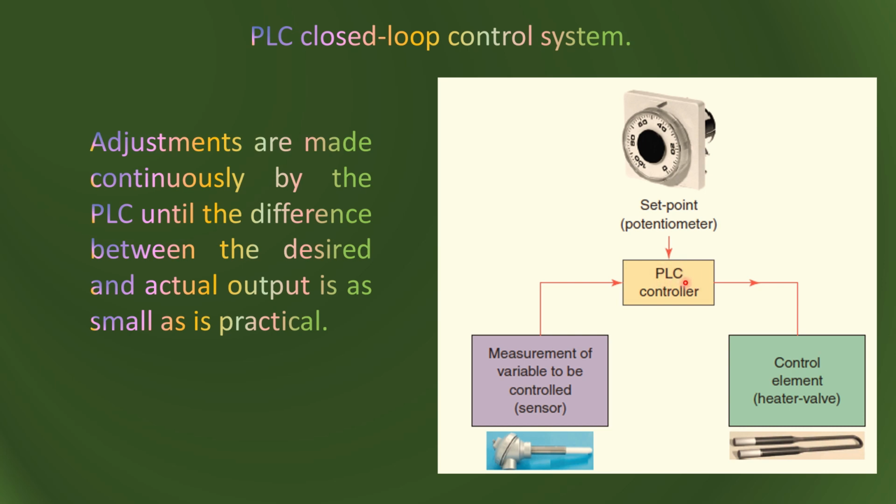So internally the PID controller or any other controller algorithm is implemented, and that controller assures that the difference between the set point and the output, which is the output of the thermocouple, is as close as possible. Then it synthesizes a control signal, and that control signal is the output of the PLC, but is an input to the element, and this signal we call the control variable. So this control variable is an input to the actuator, and the output is the process output, and most often we want to control the process output, and this process output we measure with the help of a sensor like this. So this complete loop is a closed loop. The input signal is here and the output signal is here. This is why we say it is a closed loop system.